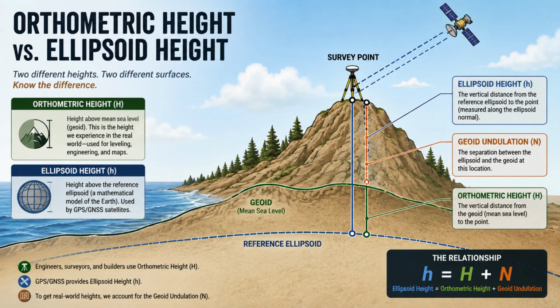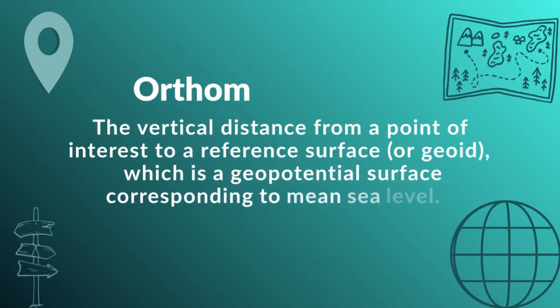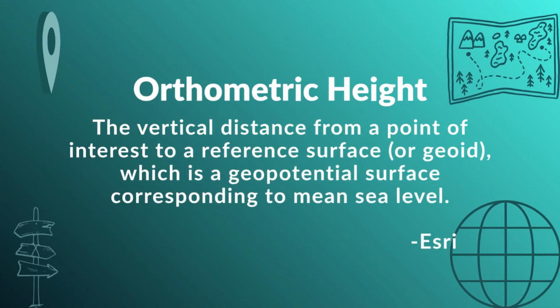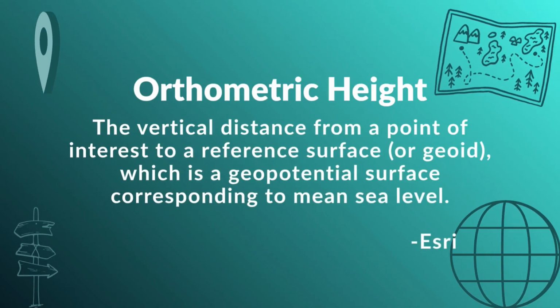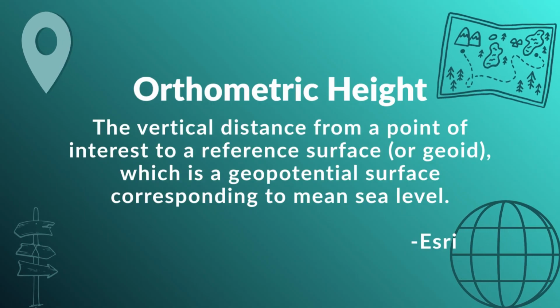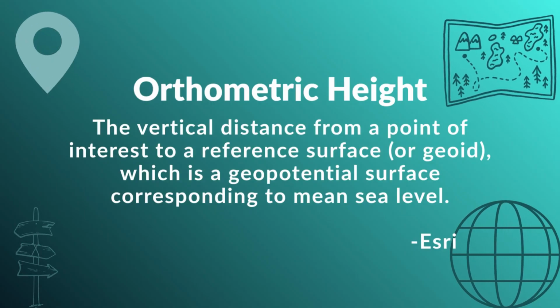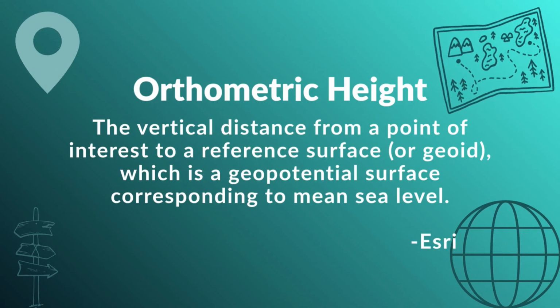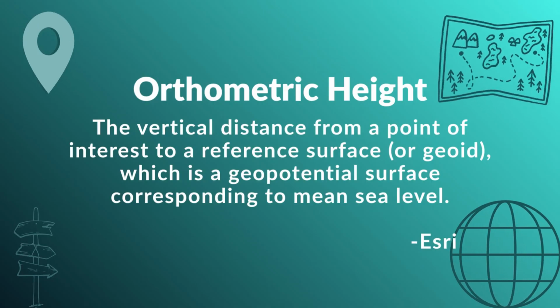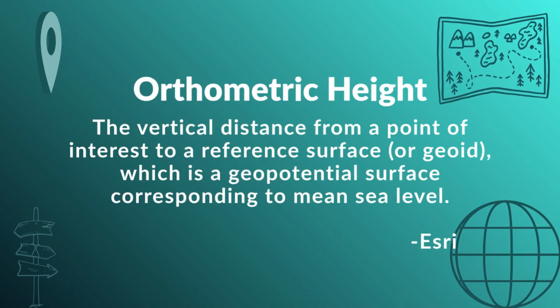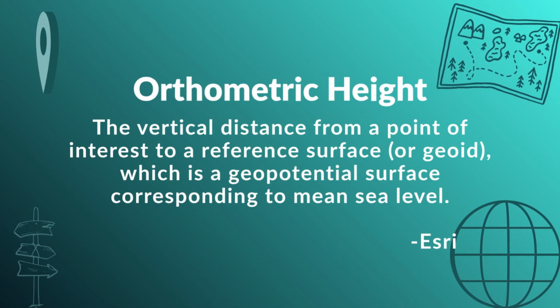Okay. If you are going to model elevation in GIS, you absolutely must understand the four distinct types of heights. Okay, let's break them down for the listener. First up is orthometric height. I'm assuming this is what most people casually think of as just true elevation, right? Right. Because it's measured relative to the geoid. Correct.